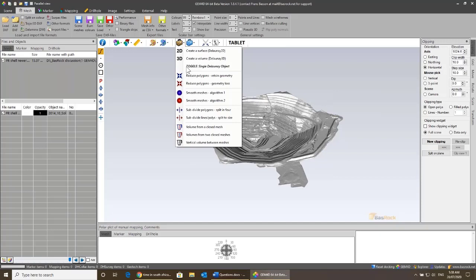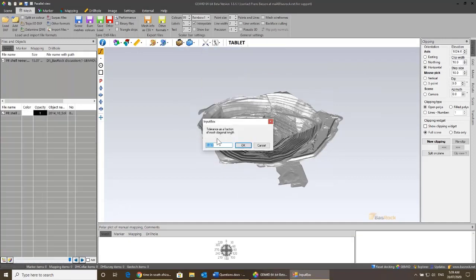So for this example, because there's one object, it doesn't really make a difference. But because it's open pit, I'll tick it on, because then it will take every object in the scene and it will drape a surface on all those. Well, it uses the points when it drapes these surfaces on. So let's see how it comes out. So I'm going to say yes, drape a Delaunay surface. It's going to ask me a tolerance. Now, the smaller this number is, so that's the default tolerance, the smaller the number is, the more finely divided this surface is going to be on that new surface. So I'm going to just make extremes. So I'm going to say 0.1.